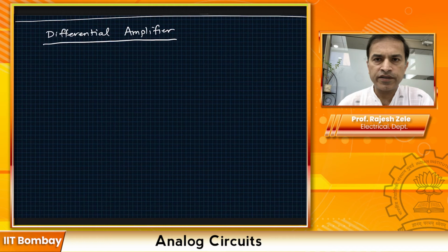When you're trying to measure ECG, for that matter, you're connecting, let's say in this particular case, two probes to your body, and you're looking for the difference in the voltage between these two probes. So the difference between the two probes is a very small value. It could be in the microvolts range, and the common mode signal which you see when you touch the oscilloscope probe can be very high. It could be in millivolts.